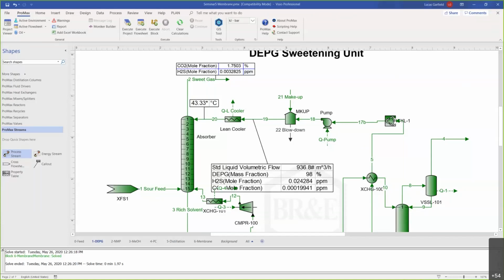Activated MDEA, I think at very, very low gas pressures, I'm not sure how activated MDEA would perform. It's something that you'd probably have to try. It would depend on the partial pressure of CO2, even if it's low pressure, it would still depend on the partial pressure, I suppose, and how much CO2 you needed to